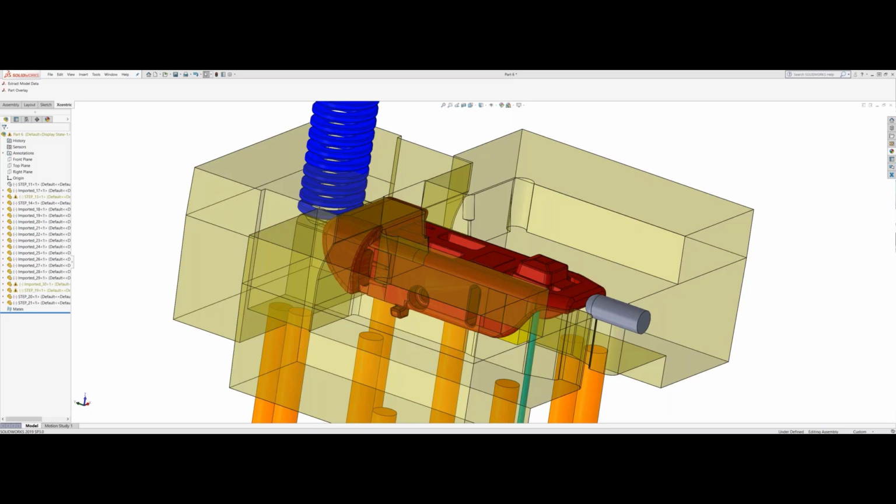Well, there's a couple ways you can do color, and it's really going to depend on the project again. So if we're doing something low volume or prototype and it needs to be close, we'll do what we call salt and pepper. We will have a colorant generated to the Pantone that's needed, whatever that may be. It could be your brand color. What we do is we'll send the material out and have a master batch of that colorant generated that goes along with the material. And then we mix that during molding. It gets blended with the natural material, and the parts come out in color.